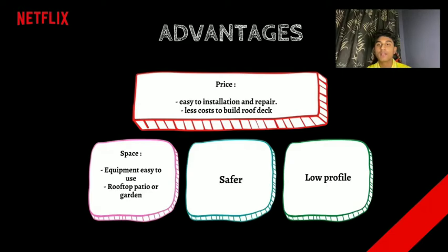You see, asphalt shingles are layered. Half of one shingle is underneath half of the one above it, so there's always at least 2 layers of asphalt shingles at any point on your roof. Under every roof system is the roof deck.